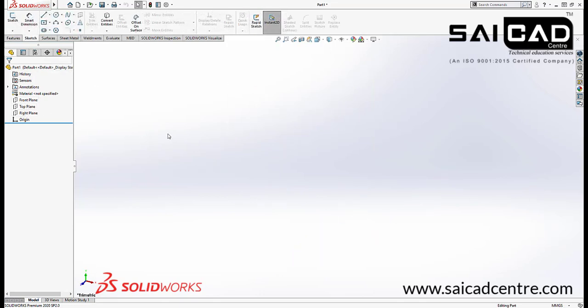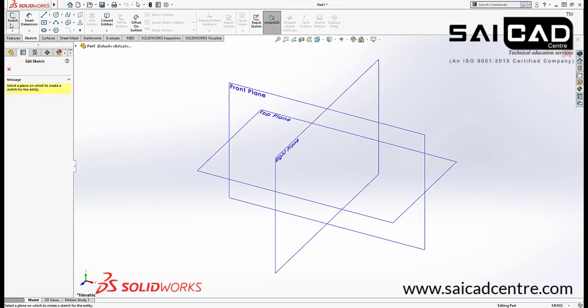Now we have the sketch tools right here. In order to create a surface, we need to create some entities, either from a sketch or from curves directly. So first I'm going to create a pipe directly from here. I will show you some tools directly from here. Like, we are going to create a sketch, so select the sketch from here, then you have to choose the plane.